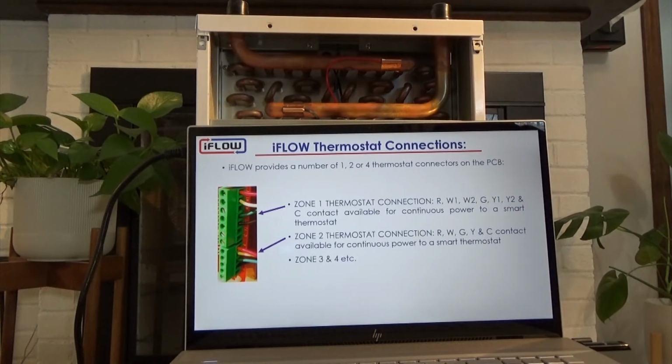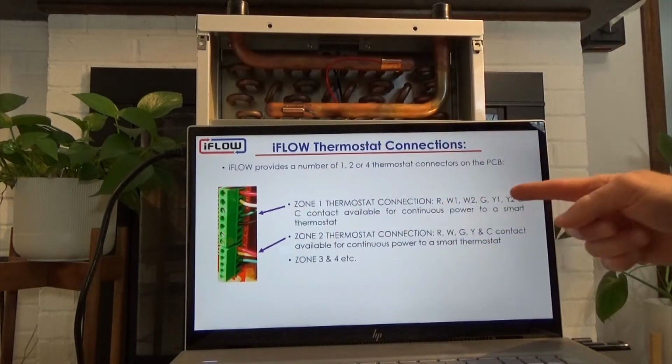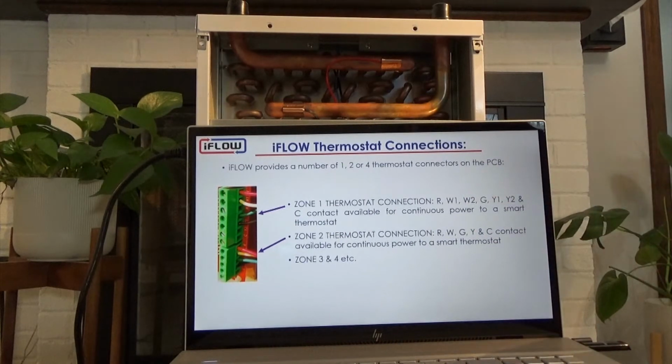So this is where a lot of the wiring confusion comes in. So just bring your regular contacts in, and that's all we need from the thermostat. So you actually don't need an expensive heat pump thermostat. You can just run with a conventional thermostat without problem at all.